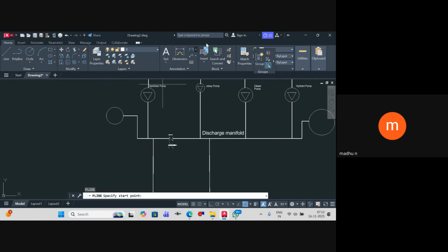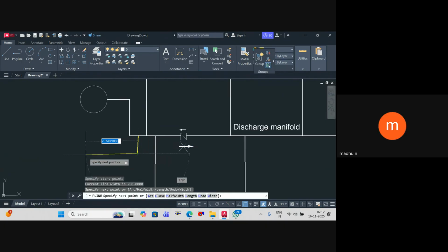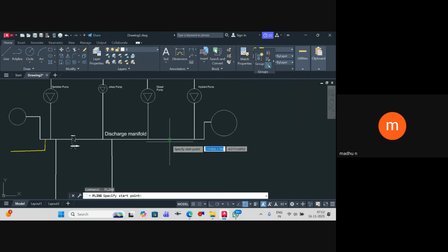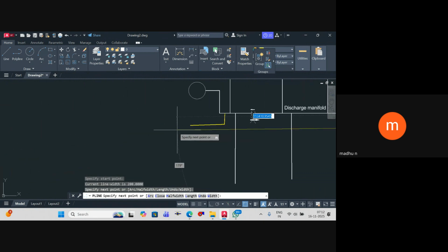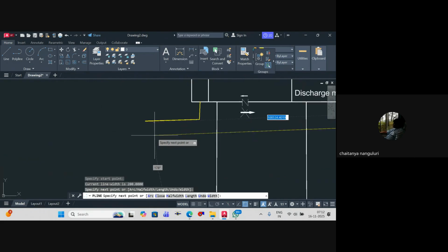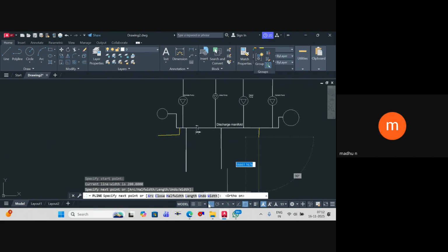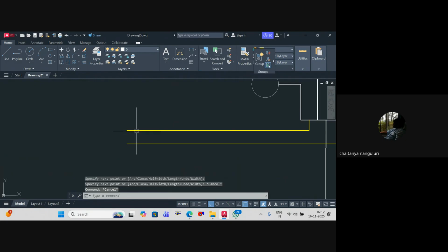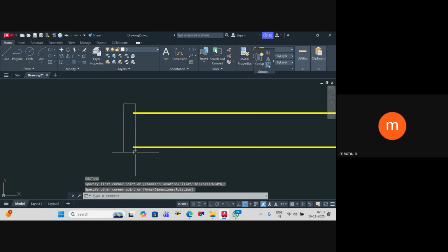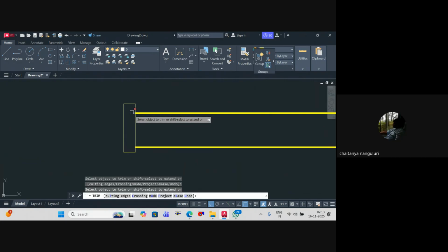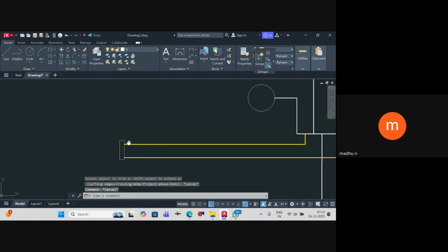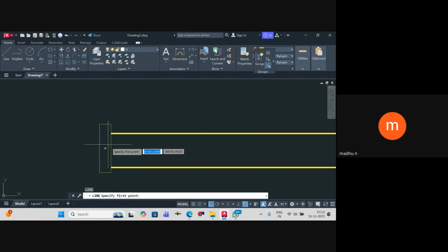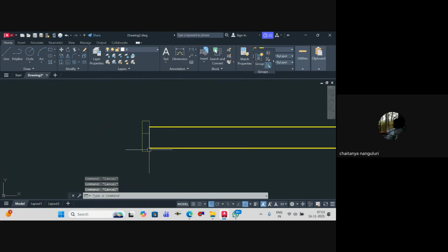So basically, what we'll do is we'll take one more. Change it to the other color. From here, you'll take small piping. From here also, you will take a small tap off. Any room corner or anywhere, we'll basically take it. Okay, don't worry. So let's take something like this. A small 25 mm pipe is also sufficient for this. So here, we'll have piping in this particular connection. One more small pipe, probably a 50 mm pipe or a 100 mm pipe, it's up to you. And then you have a small separation also in between. So here you'll have the pressure switches.